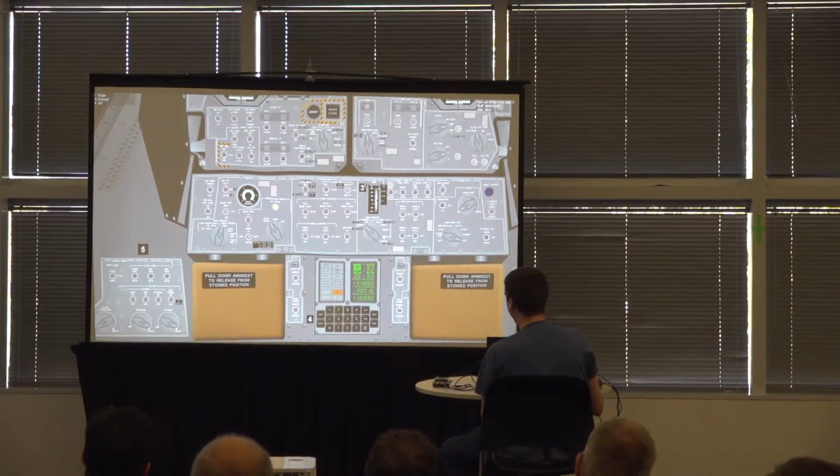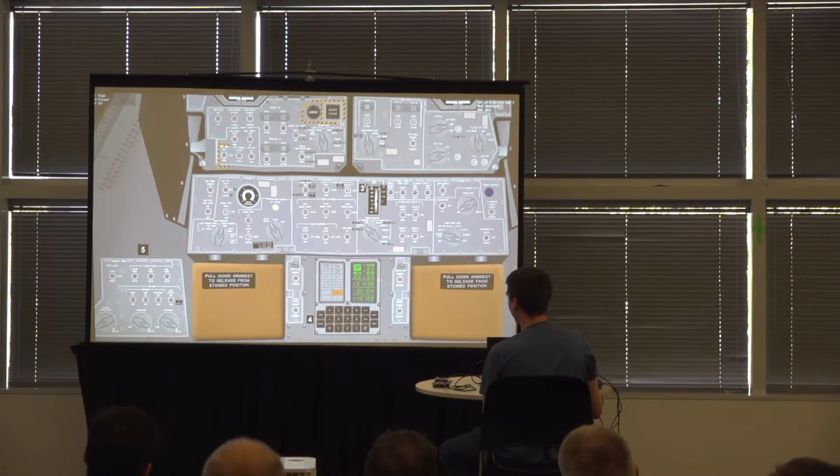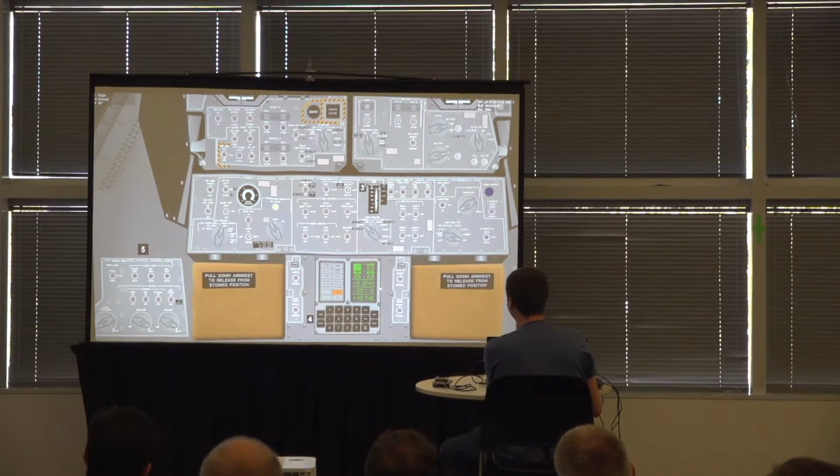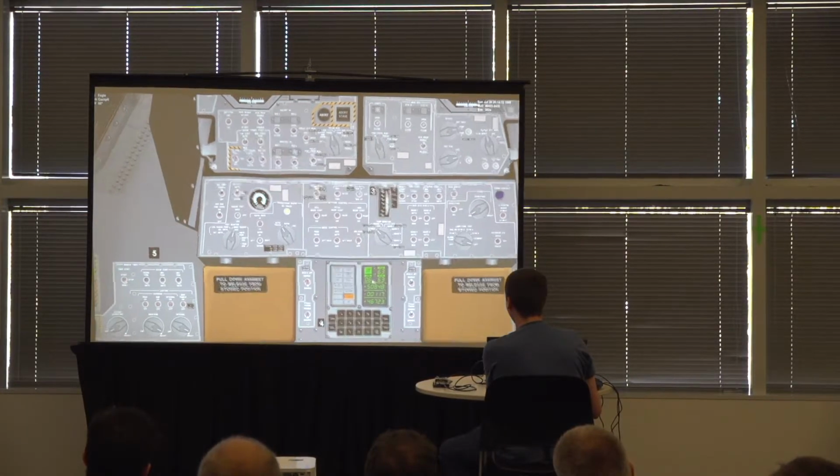And so the display on the DSKY has changed to noun 63. Noun 63 still has the surface relative velocity in the top row. You can see it counting down since we're firing our engine now. The second row has changed to our altitude rate, so we are going down at 5.6 feet per second. And the last line is our altitude, 46,878 feet. You'll notice that I'm saying point here, 8.7 feet per second down. The astronauts had to memorize the location of the decimal point in every display because the display doesn't have any points in it. So that's an additional challenge to memorizing all the noun codes.